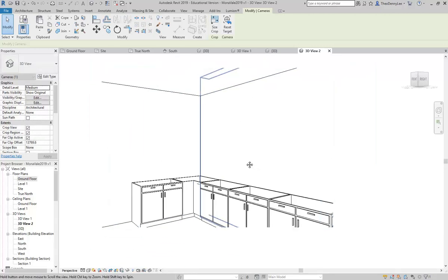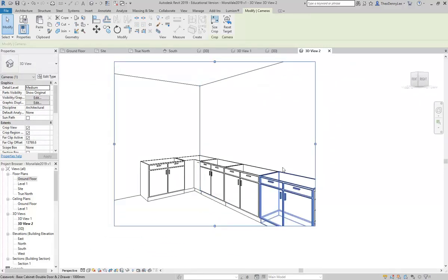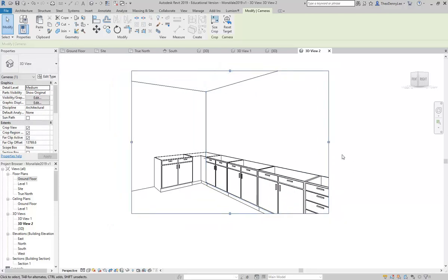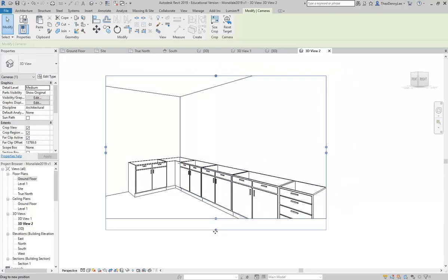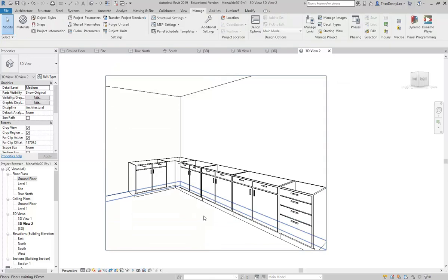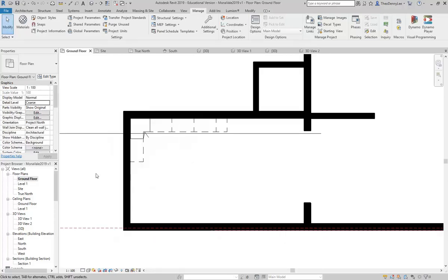So we've got a set of cabinets with no bench on top, and this is exactly how you will build them. I used to work for a furniture maker, and this is what we would do, build them like that, and then come in and put the bench over the top after. That's why it's easier to do it this way, because when you make the bench, then you can cut out the holes that you need for your sinks and other things as you go.